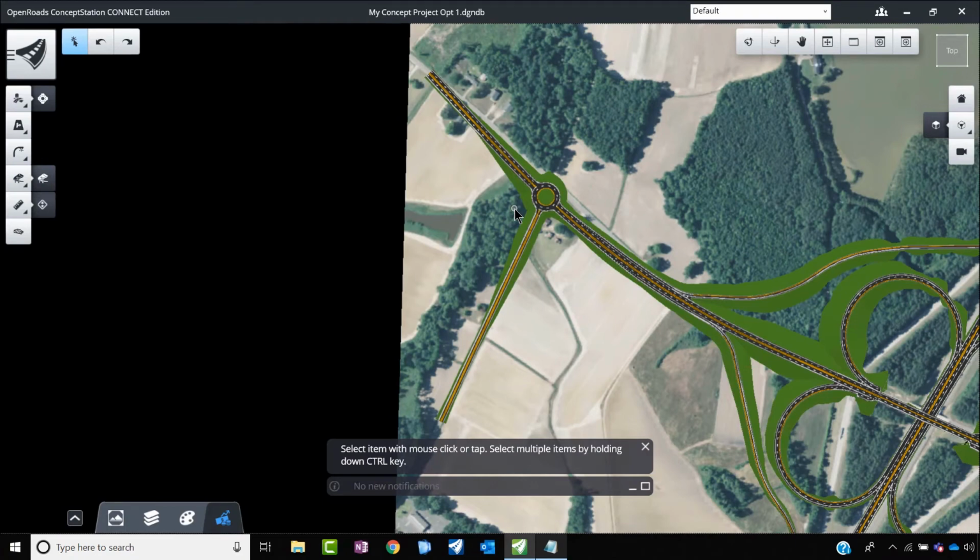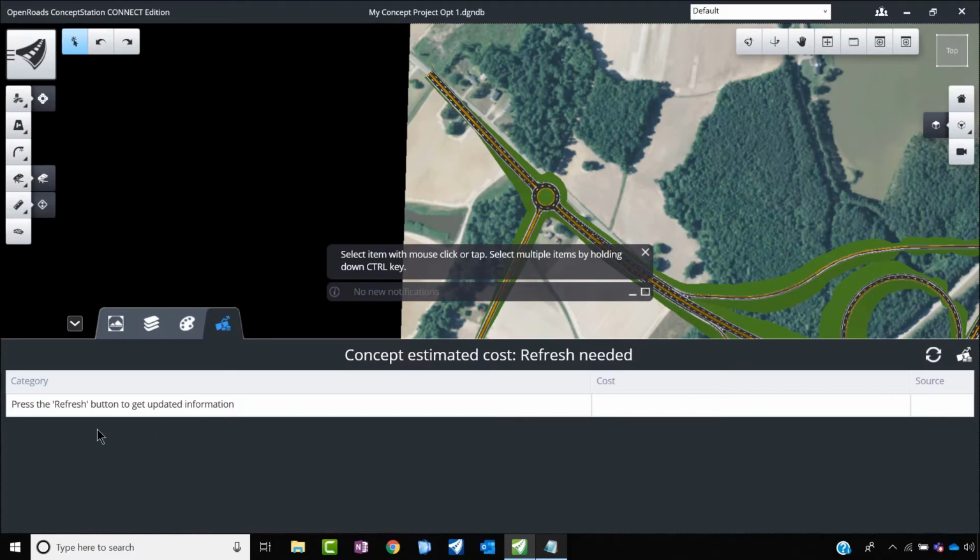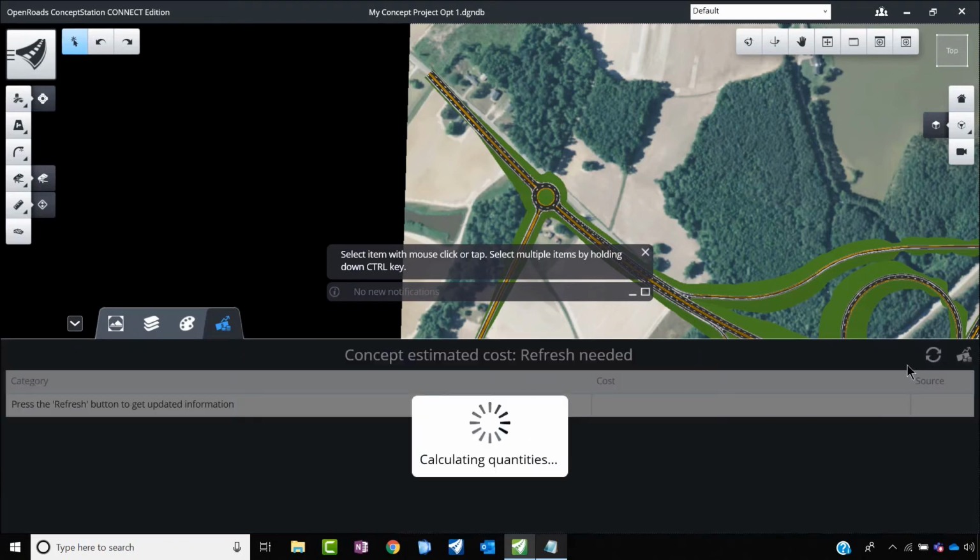So once you're done in creation of these ramps, intersections, bridges, your main roads and the secondary roads, let's have a look at the cost. For that, under this action center, let me go over here. You will see this quantities and cost tools over here. Let me go ahead and give this calculate quantities and cost.